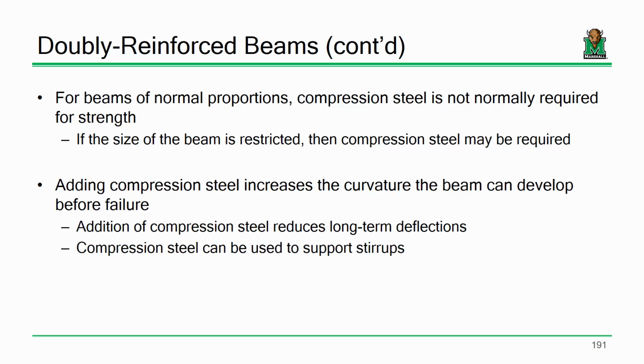Okay, so creep actually sort of flies in the face of everything that you learned in mechanics of deformable bodies, but it happens, okay? When you take mechanics of deformable bodies, you think, okay, load and displacements are always proportional. In other words, if I have a bar and I yank on it, it will displace. If I yank on it more, it will displace more. But to make that bar get longer, I have to yank on it. Creep is where the bar gets longer, but the load doesn't change at all. Okay, and that doesn't really make a lot of sense, but think about it like this. I have here a piece of chewing gum, and imagine if I hung this piece of chewing gum up and I attached a weight to it and then just left the room, came back an hour later.